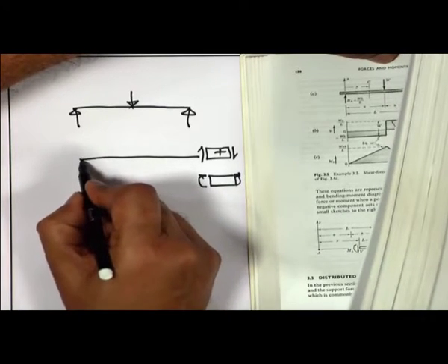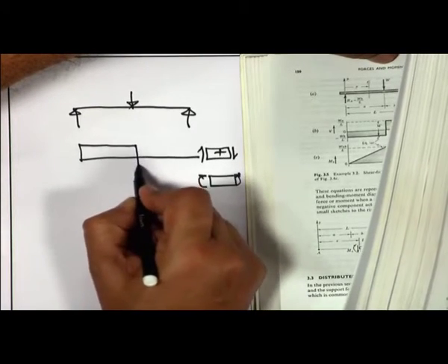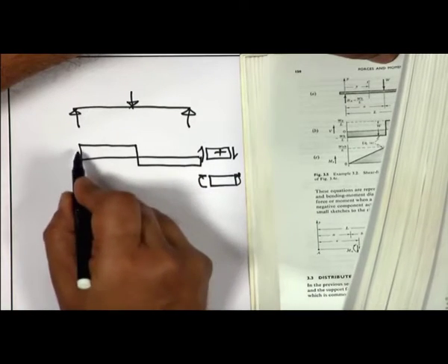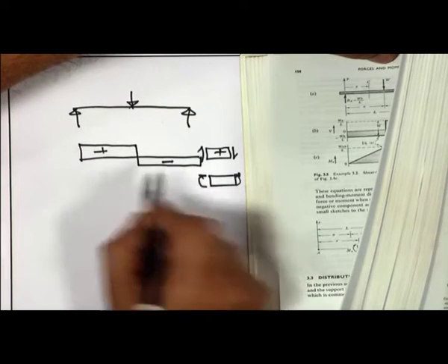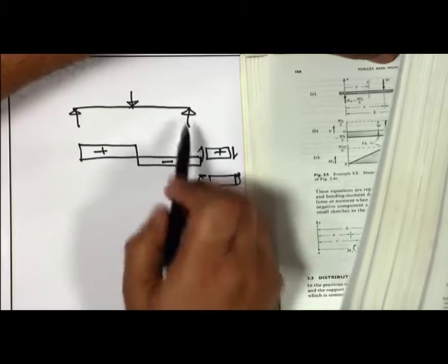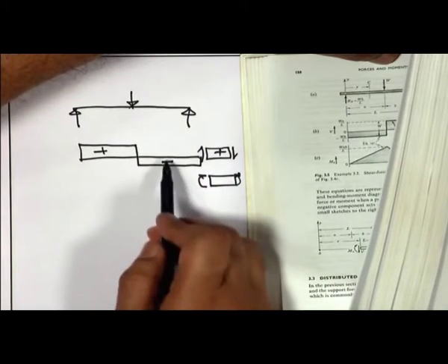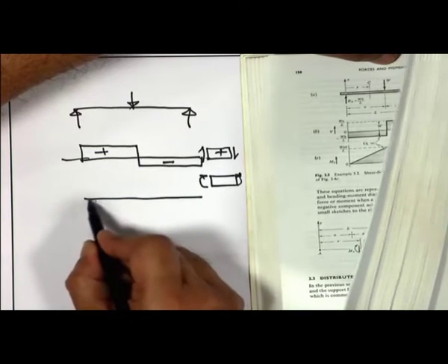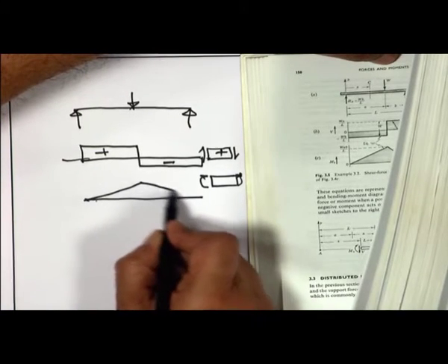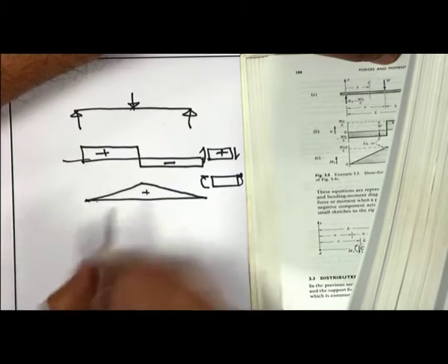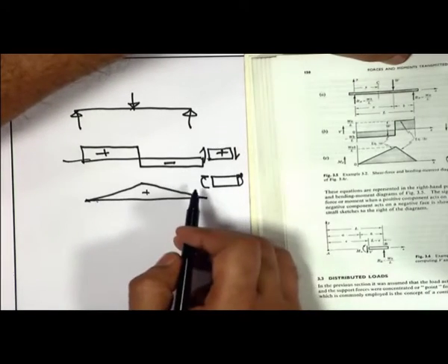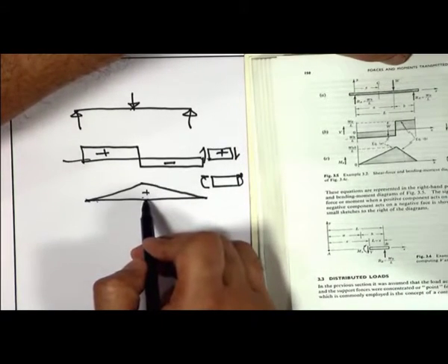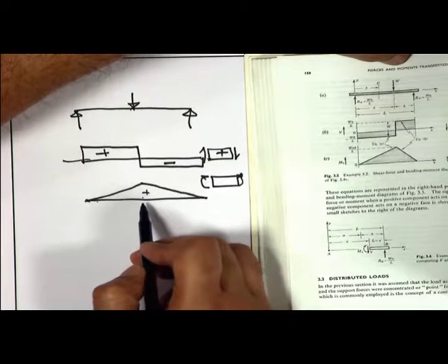So, for me the same shear force diagram will be drawn like this, where left up is positive and right down is negative. According to this, this is negative shear, and this is the middle line, and for the bending moment I have the same thing. There is no issue with that. Now, I am not putting the values. One thing is in which direction I will plot the bending moment; that also differs from books to books.